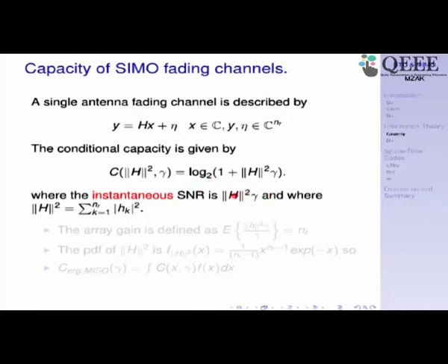So this you can work it out and get it as the norm of h squared by gamma squared, where the norm of h squared is basically the sum of squares of elements of the vector or matrix. This is also called the Frobenius norm, or L2 norm for a vector or matrix. Remember that. You have the SNR multiplied by the varying term, the random variable, which is again a summation of squares of different NR random variables.